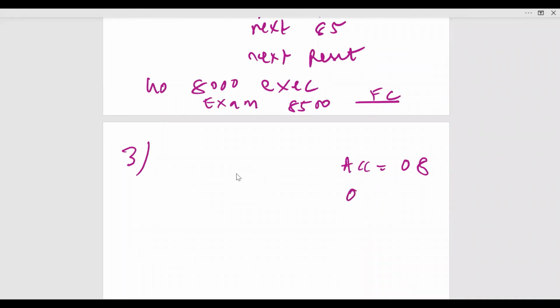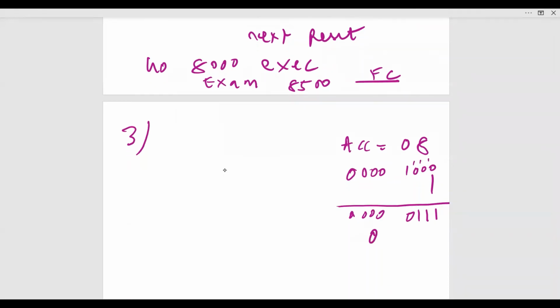So first write the equivalent of 08, that is 0000 1000. So if you decrement, it subtracts 1. So it becomes 0000, and the last bits 1000 minus 1 becomes 0111. So it is nothing but 0 and 7. Now let us write the program again. MVI A, 08.